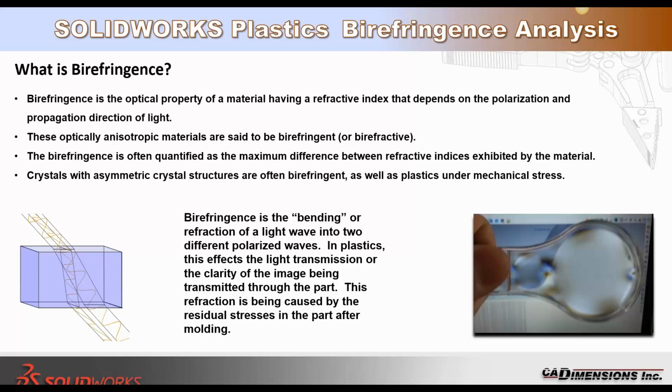Now, in a physical environment, you'll probably only be able to test for birefringence using your physical testing setup once the part has been molded and ejected from the injection molding machine. Using SolidWorks Plastics, you'll be able to see birefringence at the end of the different stages in your injection molding process, at the end of filling, the end of pack, and of course at the end of warping as well.